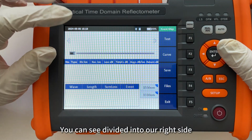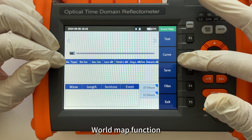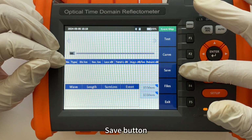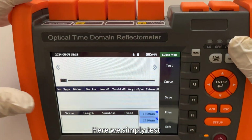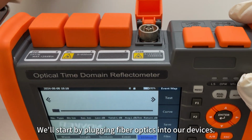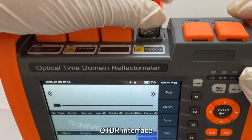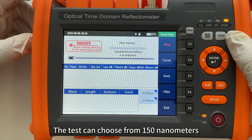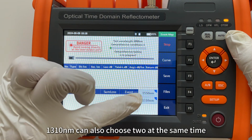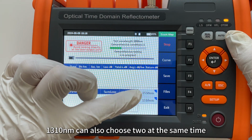On the right side you can see the test start button, event map function, save button, and file function. Here we simply test. We'll start by plugging the optical fiber into our device. In the OTDR interface, click directly to start the test. The test can choose 1550 nanometers, or 1310 nanometers, and can also choose both at the same time.